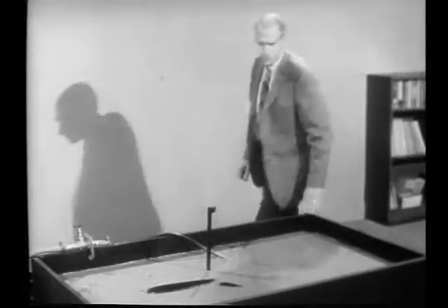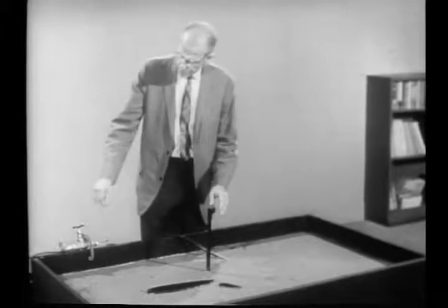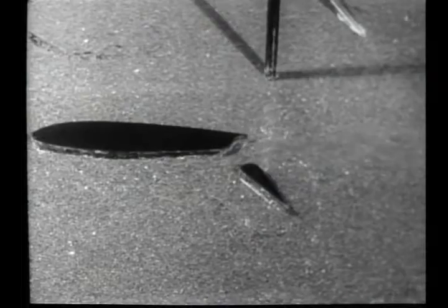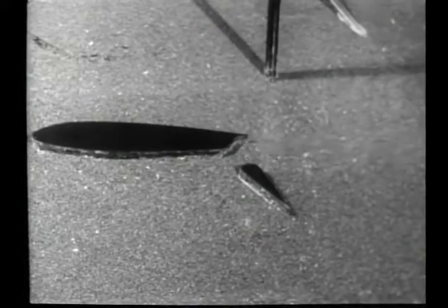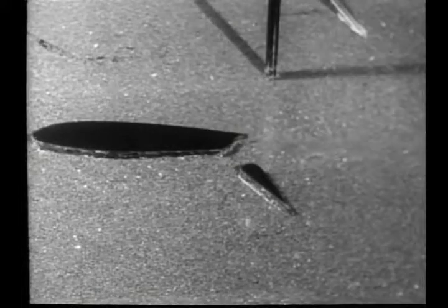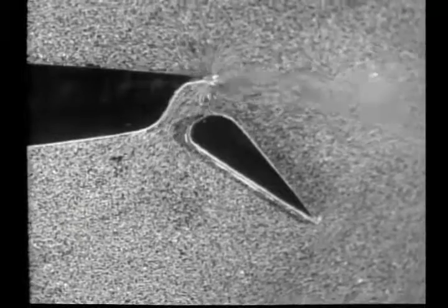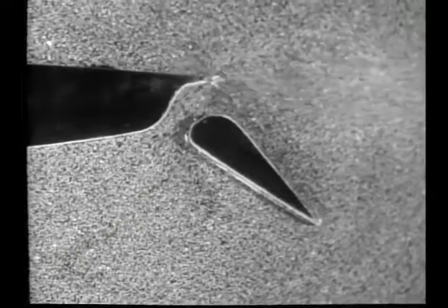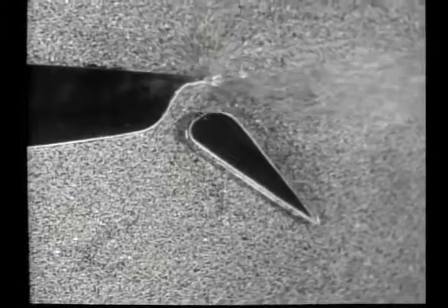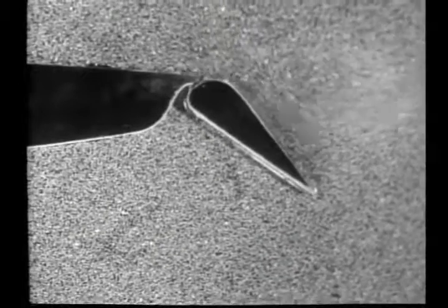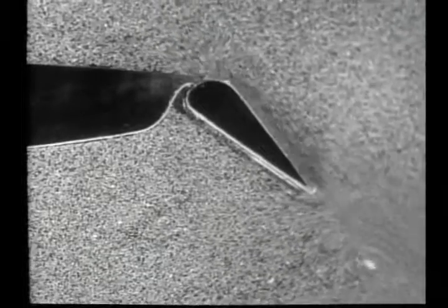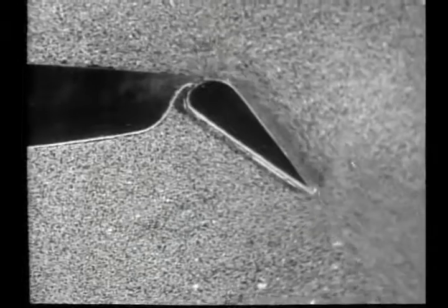Still greater effectiveness can be obtained from blowing jets if they are produced by the direct application of power rather than by the limited differentials available on the body itself. The jet, moving at high speed through the surrounding fluid, creates regions of high viscous stress at its edges, and as a consequence drags substantial amounts of fluid along with it. When such a high-speed jet is near a curved surface, the interaction of the boundary layer with the jet causes it to bend and to adhere to the surface. This is called the Coanda effect. Here it is used to conduct the jet momentum to a region where separation is most likely to occur.